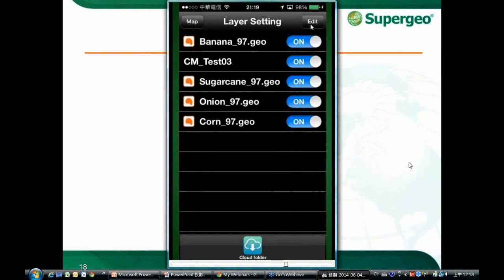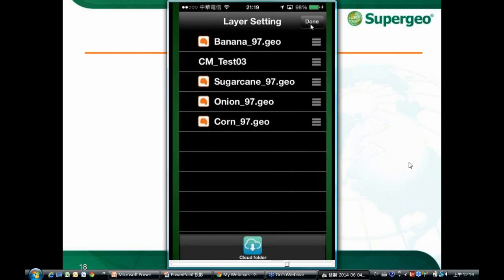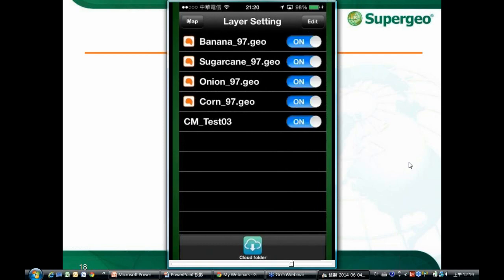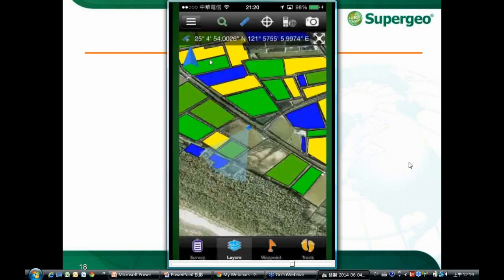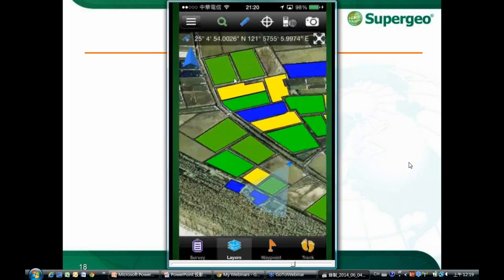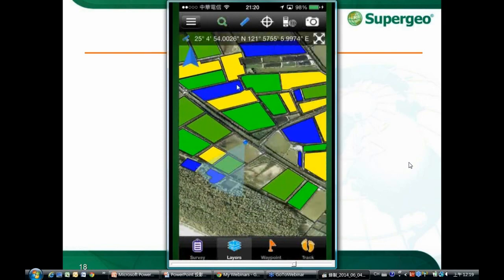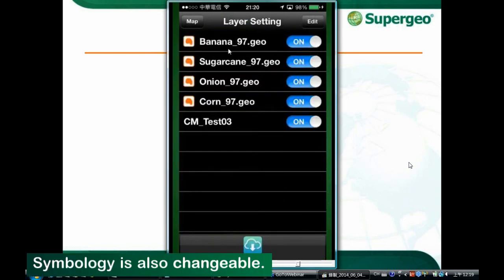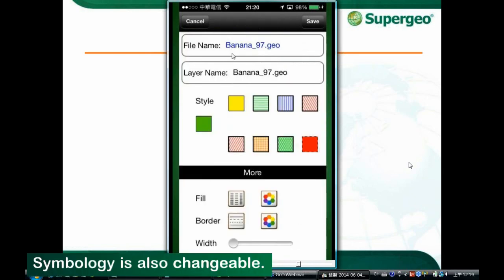Can you explain the four different formats? For example, PRJ or... Okay. The PRJ format is the projection file, which is really needed within SuperSurv. The .shp format is the geometry, and the .dbf format is the attribute table. And another one is the CPG, which stores all the other settings. Yeah, code pages.